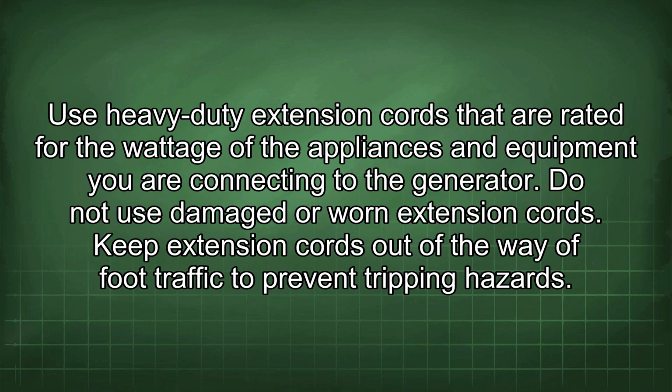Use heavy-duty extension cords that are rated for the wattage of the appliances and equipment you are connecting to the generator. Do not use damaged or worn extension cords. Keep extension cords out of the way of foot traffic to prevent tripping hazards.